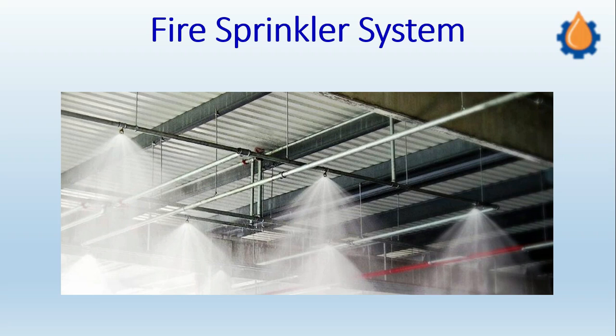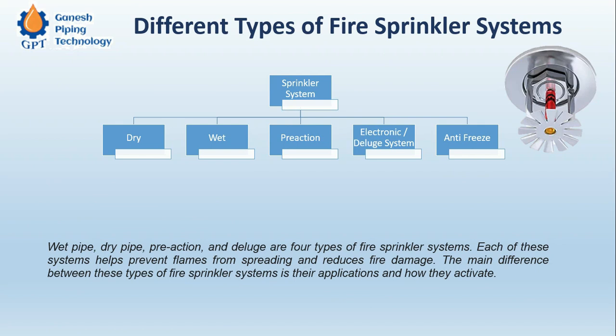For example, in a godown where there is very little movement, and if there is a momentary fire and it spreads, the fire sprinkler plays an instrumental role in restricting the spread of fire. How it works, we will see in the coming slides. Basically, it lowers the temperature of the surroundings, and thereby restricts the spread of fire.